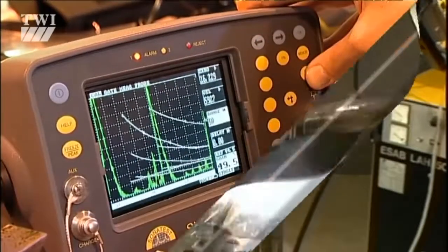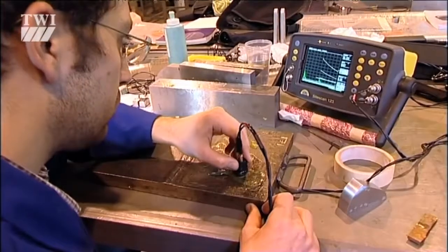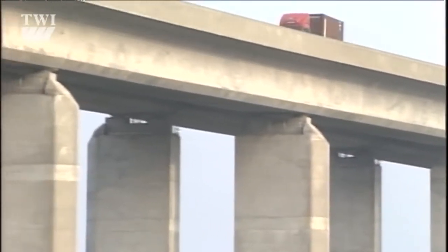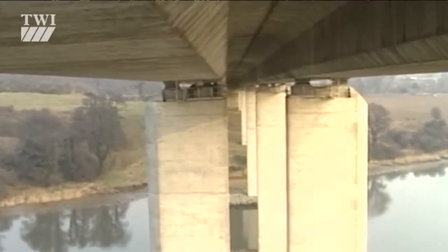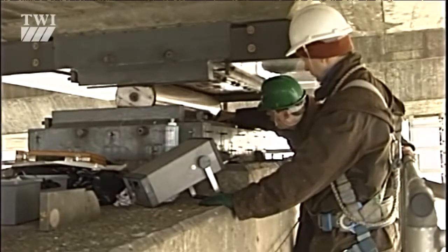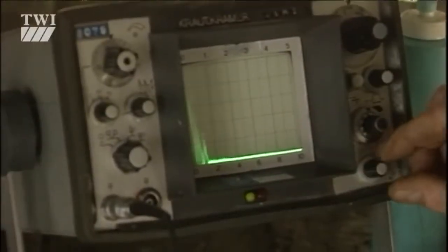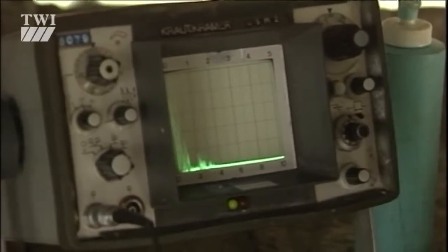So now to surface ultrasonics. It tends to be used for the detection of environmental cracking in petrochemical plant, and also fatigue cracks in civil engineering structures like bridges. As the name suggests, surface waves travel along the surface of components, penetrating to a depth of only 1 ultrasonic wavelength. It's used to find planar flaws that break the surface and lie at 90 degrees to the scanned surface, such as fatigue cracks in weld toes and also stress corrosion cracking.